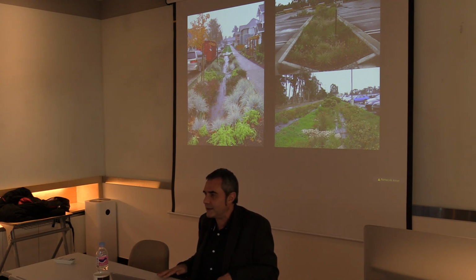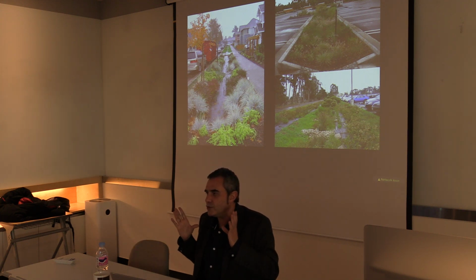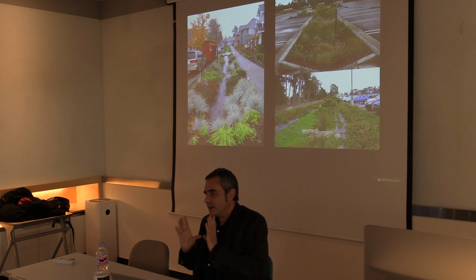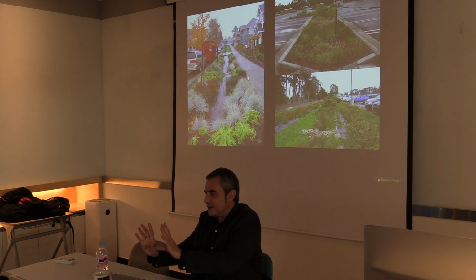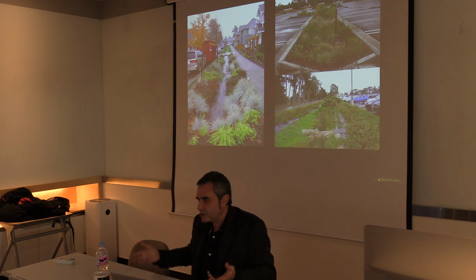So without necessarily removing all the asphalt, if we are able to create channels where the water is collected, the water is partially purified by this system. So instead of using a sewer that collects the water quickly and takes it to the purifying station, the water is already being purified in the street, and is growing vegetation, and is absorbing carbon, and is producing evapotranspiration.